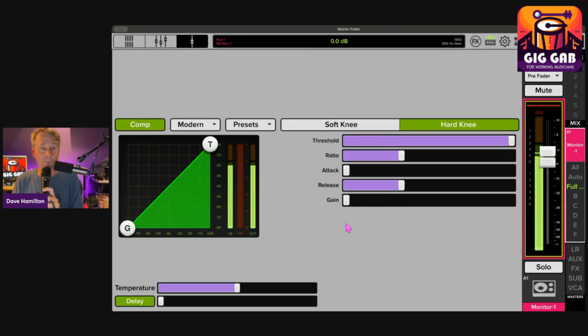You can put compression on an output. You can see that the compressor is on this one, but there is no makeup gain, and the threshold is well above anywhere the speaker would go. There's no gain reduction happening. Generally speaking, I wouldn't put compression on a monitor speaker because you're just asking for an opportunity to create more feedback or amplify feedback that is there.